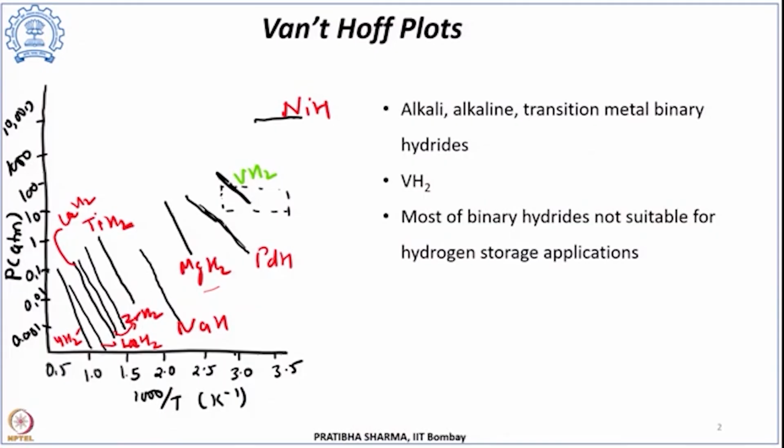If we look at the high temperature hydrides, the hydrides which at an equilibrium pressure of say 1 bar desorb at temperatures higher than 700 degree centigrade, typical examples are zirconium hydride or lanthanum hydride. Zirconium hydride has a very high desorption temperature, although its volumetric capacity of hydrogen storage is high, about 119 grams per liter of hydrogen being stored.